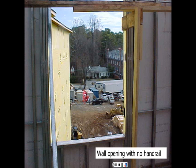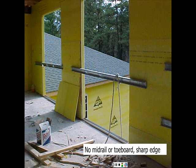Here we have a wall opening with no handrail. If someone is leaning out of this window to do any work, they may fall. Here we have a top rail, but no mid rail and no toe board. And even with the top rail, it's like a C channel. It's like a metal stud. So yes, it can resist the 200 pounds, but it has sharp edges which might injure the person it's trying to protect.